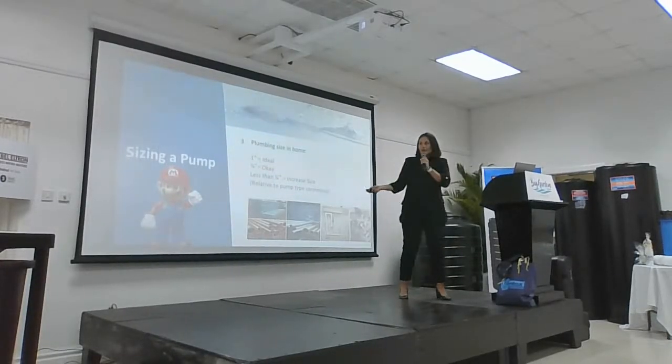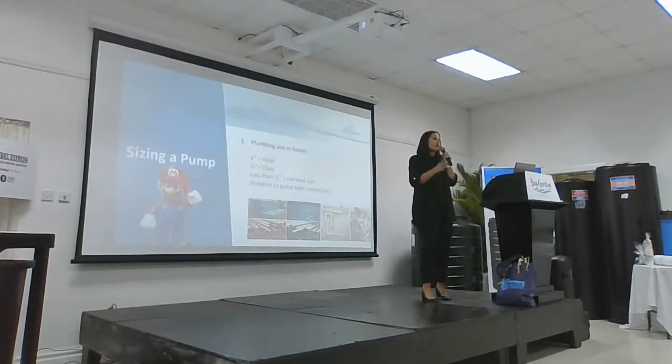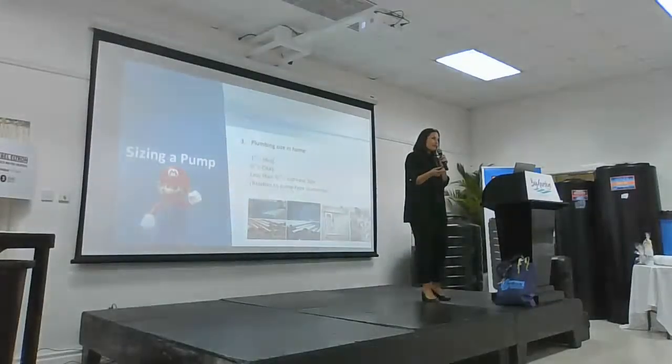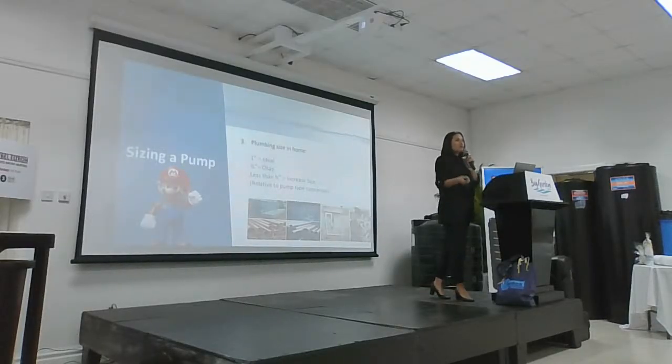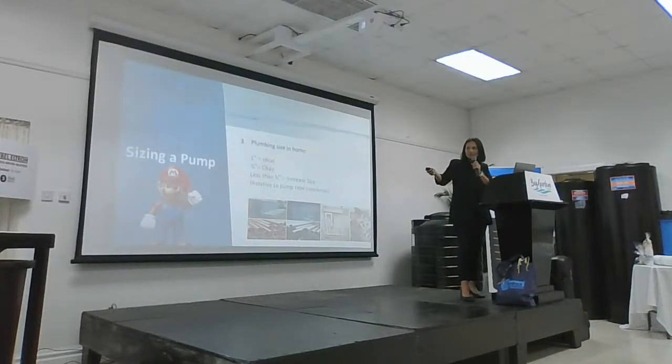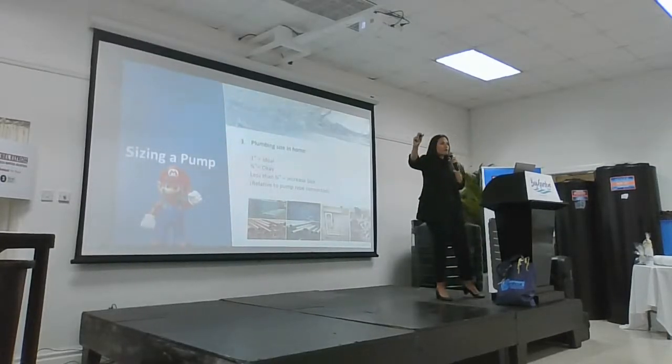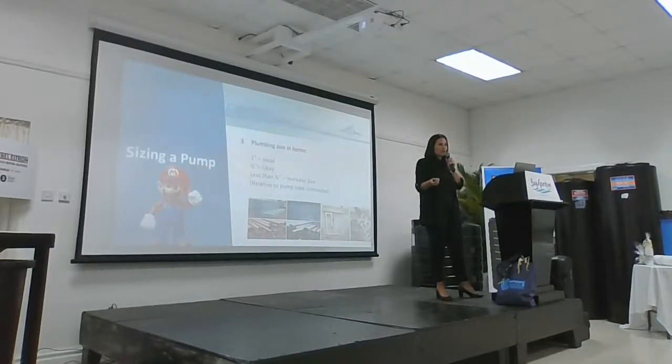These pump manufacturers, Pentax, would like you to install your pump with 1 inch plumbing. The reason being, especially important for the suction, is that you don't starve your pump. Don't make it work harder for the water that it needs. And then on the discharge, if you can maintain 1 inch plumbing for as far as you can into the home, you will reduce friction loss.